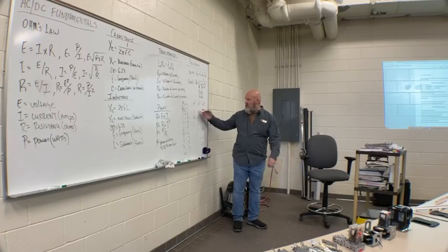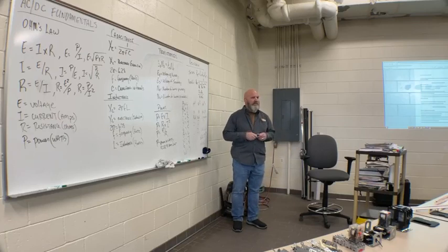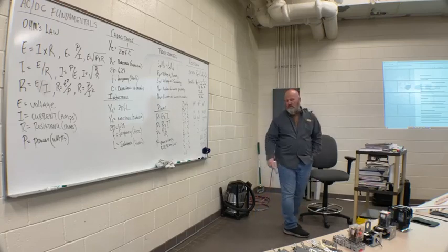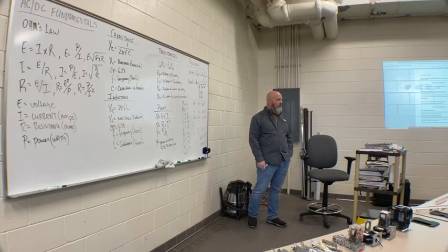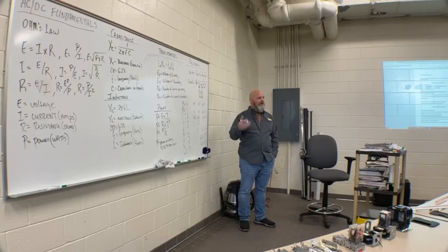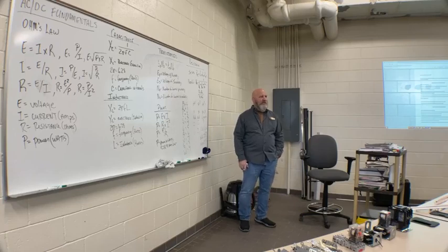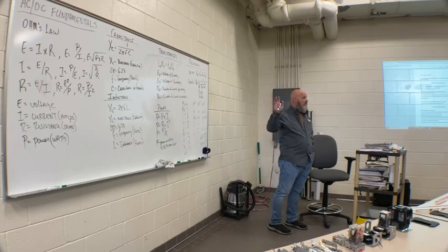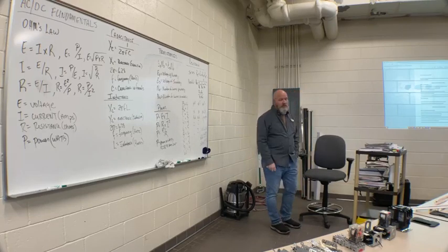I can tell the students, and they can do this part, and I say, okay, give me the minimum and maximum for you to be able to use that resistor within tolerance. They don't understand that part. So you either multiply by 0.95 and 1.05, or multiply by 0.9 and 1.1. So these are the lessons I have to go through the first class to get their math skills up to the point that they can build upon those math skills. So don't let anyone tell you that a student going through the electrical program, and I don't care if it's electrical, welding, HVAC, is the same way. You're going to have to use the math.